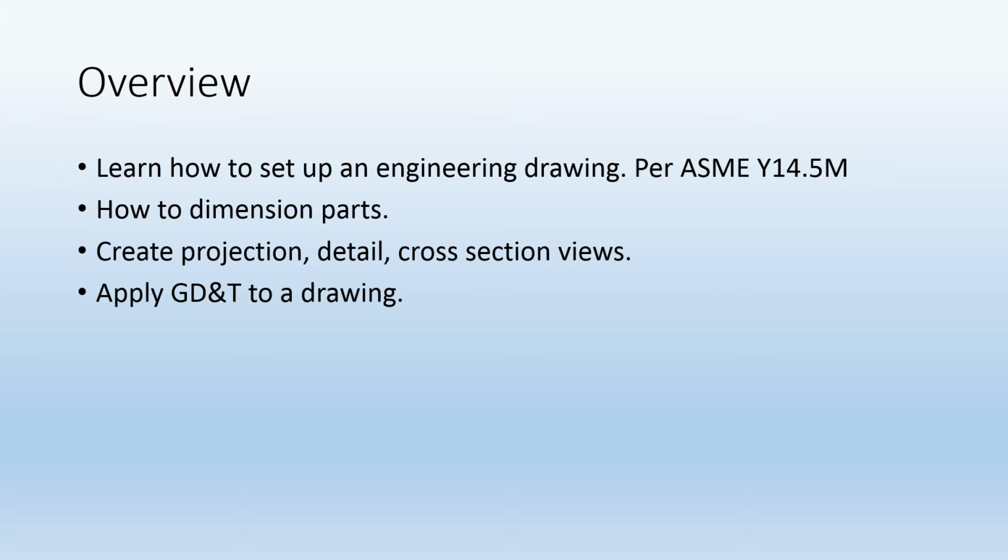So another thing which they use in the industry is the geometric dimensioning and tolerancing, where you can apply something like a position tolerance, where basically I can set a position tolerance of 10 thousandths of an inch. And what this does is you're basically drawing a circle of diameter 10 thousandths, 0.010, around that point. And as long as the center of the hole lies within there, it follows the tolerances you're drawing, and it's acceptable. There's other things you can apply as well.